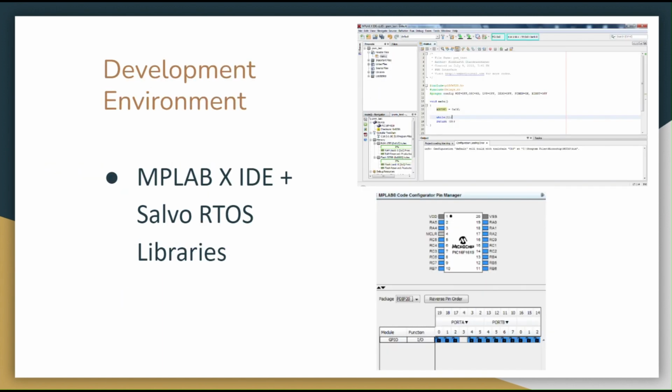In terms of development environment, I was pointed in the direction of the MPLab IDE, our integrated development environment. On the MPLab site, it claims to be an expandable, highly configurable software program that incorporates powerful tools to help the programmer discover, configure, develop, debug, and qualify embedded designs for most of our microcontrollers and digital signal controllers. Some features which make it unique among IDEs are a data visualizer, which displays real-time streaming data, and an I/O view, which personally I found very helpful when getting it set up for a basic LED Hello World application, which I will cover in a bit.